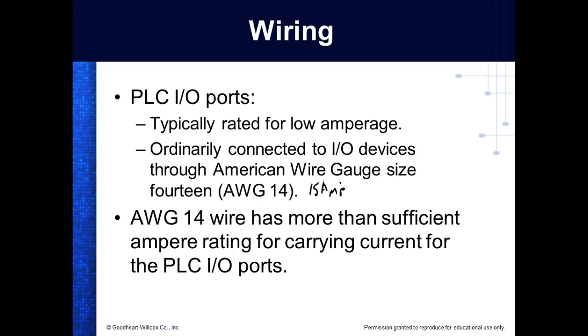If you don't know it, the thing you need to do is what? Look it up, right? So don't take for granted how much an input module will draw. Usually the input module draws very low current. The output is where your loads are connected.